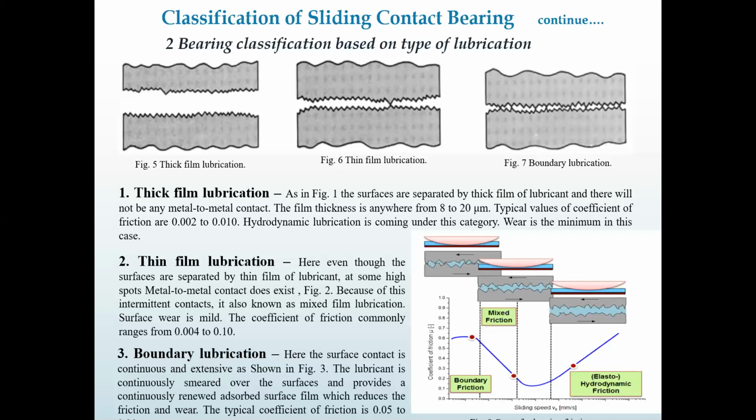Again, because the surfaces are in direct contact at their highest points, there is a possibility that interlocking will happen at the asperities, where metal to metal contact takes place. Gross seizing is prevented by the coating of lubricant on the contact surface, and because of this it is called a thin film, or boundary lubrication.